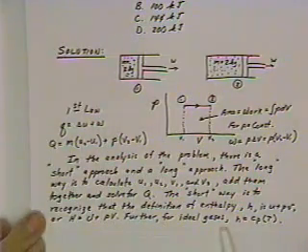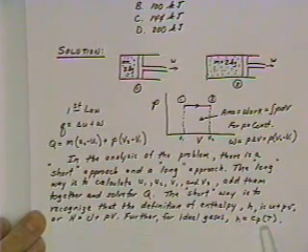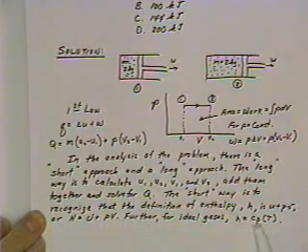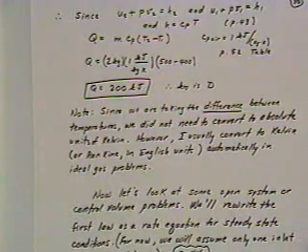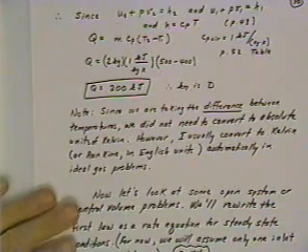We also know that for ideal gases, and that's what we're working with here, H is equal to C sub P times T. So if you recognize the shortcut on this problem, then you can combine the internal energy and pressure terms and recognize that specific heat times temperature is the enthalpy.